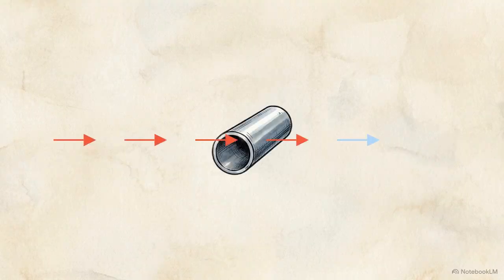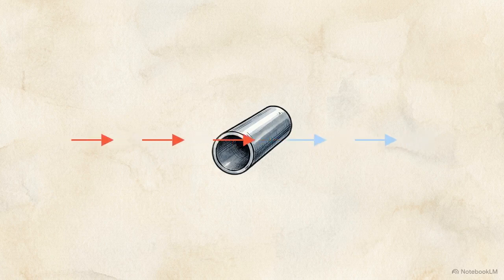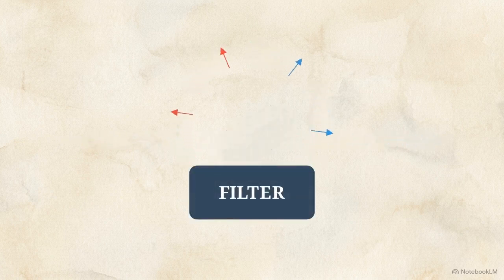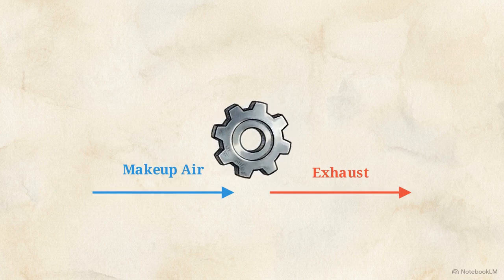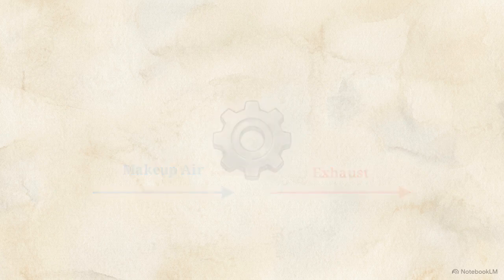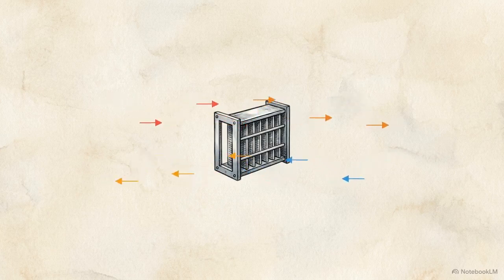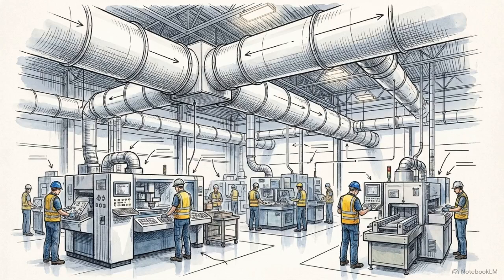Take industrial exhaust ventilation systems, where a major problem is managing the massive energy losses created when heating or cooling replacement air. We have three primary engineered solutions here: designing a closed-loop system to filter and recycle the contaminated air, introducing makeup air directly adjacent to the contaminant origin point so it immediately vents, or passing supply air through a heat exchanger to capture thermal transfer. Engineering controls like these handle physical hazard prevention.